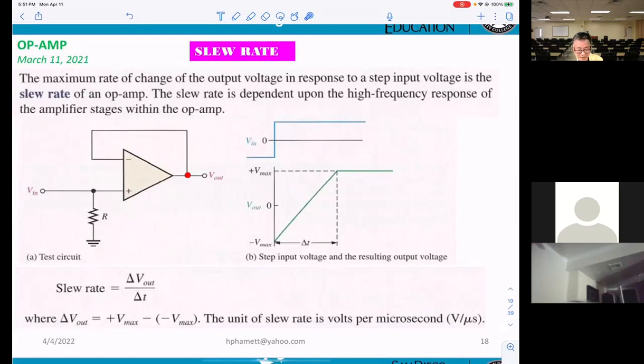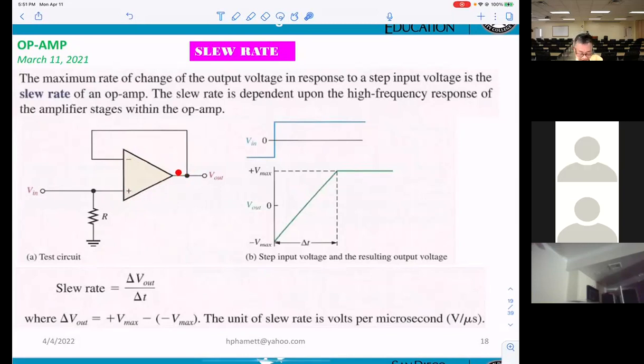Non-inverting? No, it's not, it's the follower. Follower, correct. Unity gain. You get the output connected directly to the negative input, with no resistance. That means the gain equals 1. It can be a buffer for isolation. The follower is only telling you that the input and output will be the same.